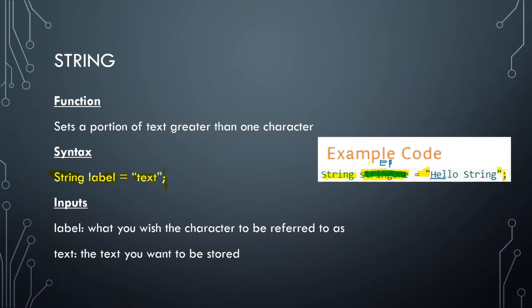It makes the code easier to write, and it's easier to change your variables. So we just have to keep in mind when we're declaring things what the best command is to use. If it's a number, integer is a really great way to declare that, especially if you're working with different pins on the board. If it's a single character or single number, we can use the character function. Or if it's a word or a phrase, we can use the string function to declare that. This also works backwards a little bit, so you can use string to declare a single character or an integer if you really wanted to, although it would be a waste.